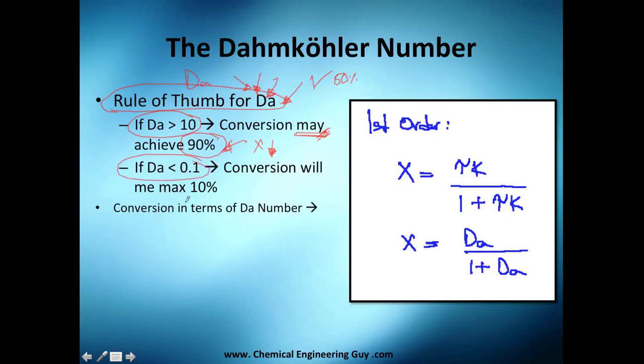So yeah, let's keep going. With a Damköhler number lower than 0.1, the conversion will be low. That means a maximum of 10%. And what does that mean? You need to improve your Damköhler number. And many times you will not be able to improve it, because maybe you make it high, but I told you once again, it's only a may, it's not a must. It will not, like, this is actually wrong. It's not a will, it's a may or might happen.